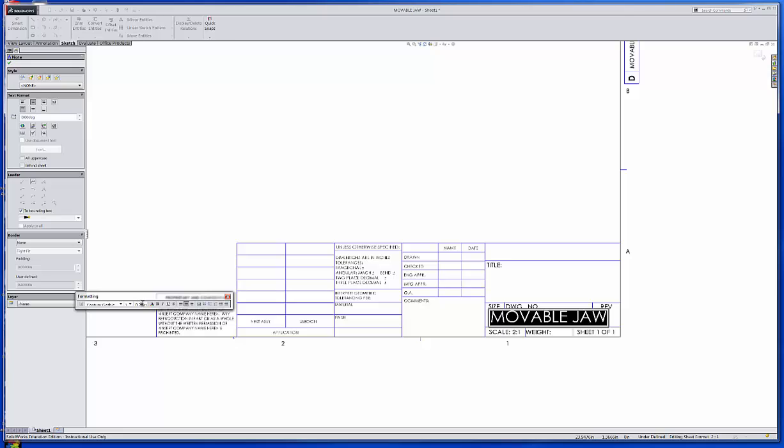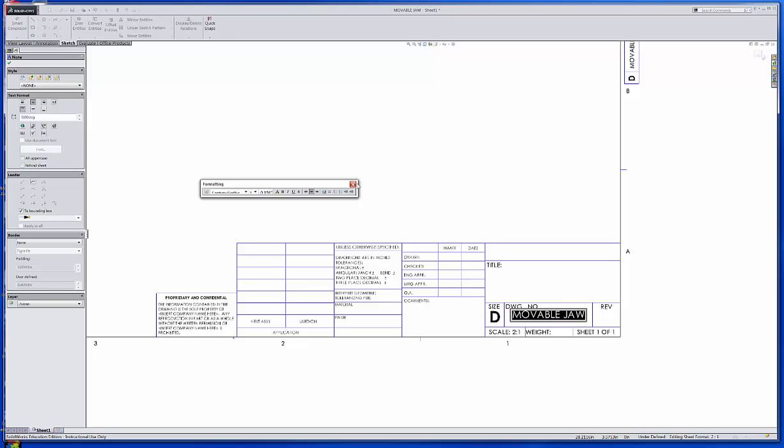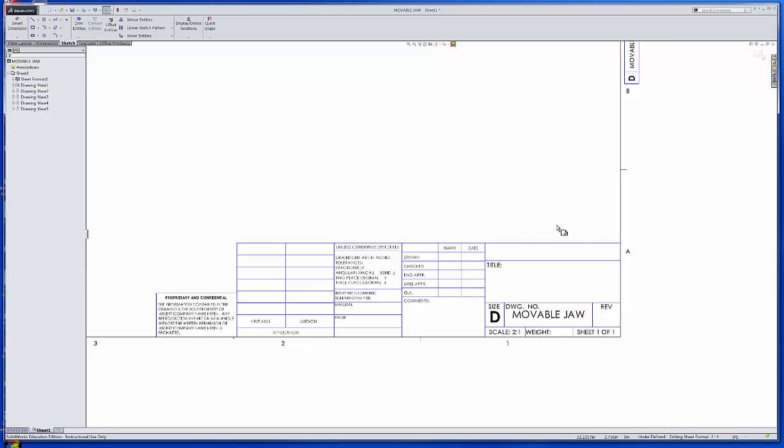It's showing that it's a 1/4 inch text height, and I'm losing that size, but I know that's 1/4 inch. Actually I'm going to go in there and delete all that, and I'm going to make it 5/32, I believe, is what it calls for in a standard drawing format, and then that'll show up a little better.